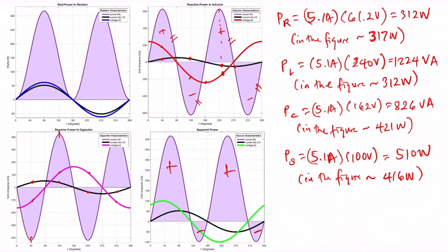The return power is naturally coming from the interaction between the inductor and the capacitor, and the dissipative power mostly comes from the resistor, but because the inductor and the capacitor are also trying to get as much power as they want, there's some sort of balance that they have to achieve. So there's also some dissipation that is occurring between the exchange.